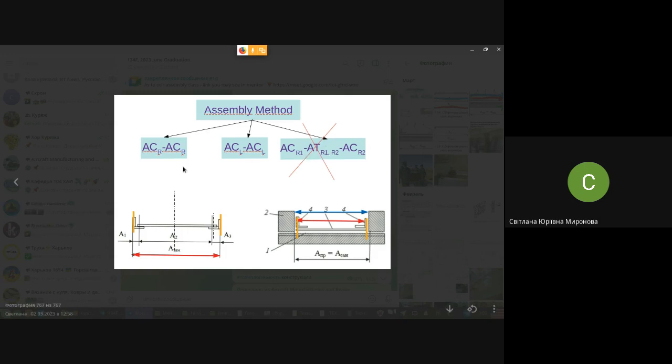And also it's important to remember about bases. Bases may be real, physically existing, so you can touch them, or bases may be so-called latent. For instance, the axis of this hole or the axis of any hole are latent bases. Sizes are shown with respect to this basis, like the diameter or radius of the hole. They are shown with respect to the center of this hole, but you can't touch the center of this hole with your finger or with another component, because it exists only in your imagination, and it may also be shown in a drawing.